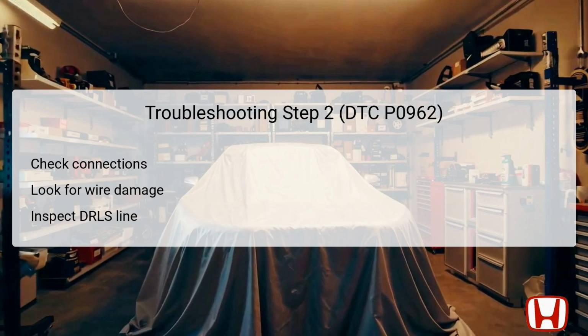Inspect the wiring for signs of damage, such as fraying, cuts, or corrosion, which can lead to an open circuit and fulfill the conditions for a DTC to activate. It's essential to ensure that all connectors are properly seated and no pins are bent. This step can often reveal visible problems that could be the root cause of the malfunction, eliminating the need for